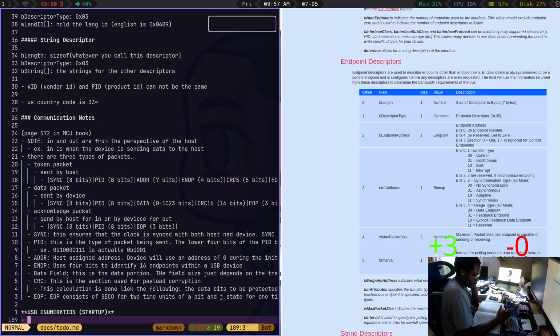After detecting that the USB is attached, the host waits 100 milliseconds to allow completion of the device plugging in, and issues a reset request. The reset request sets the device into the default state. Initially, the default address of the USB device is 0. Okay, so it's a whole sequence of stuff.